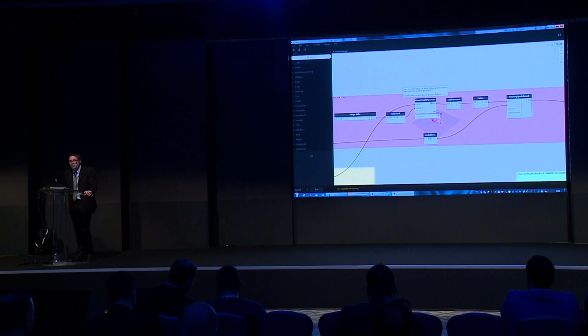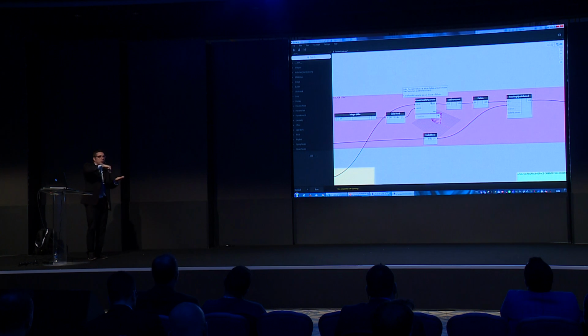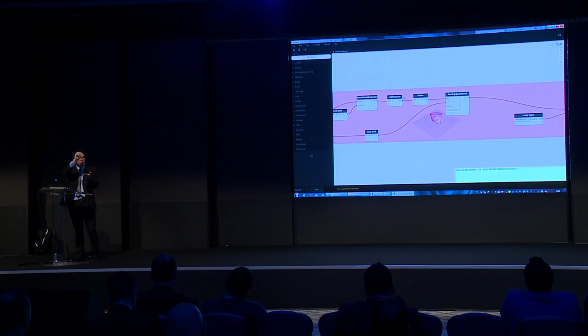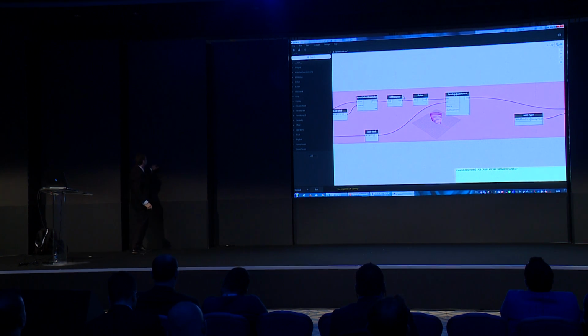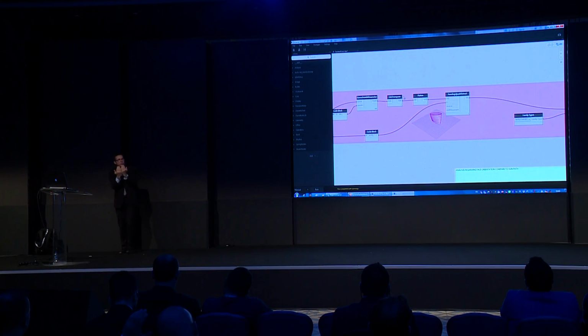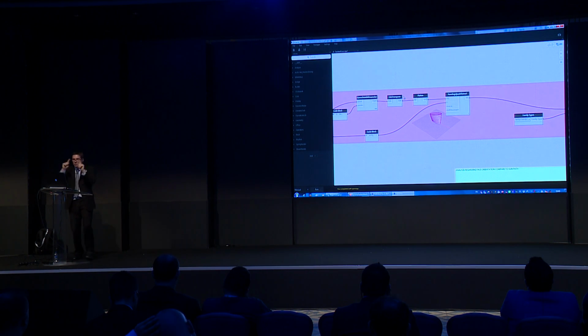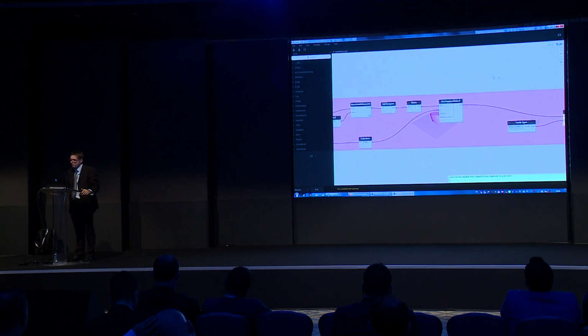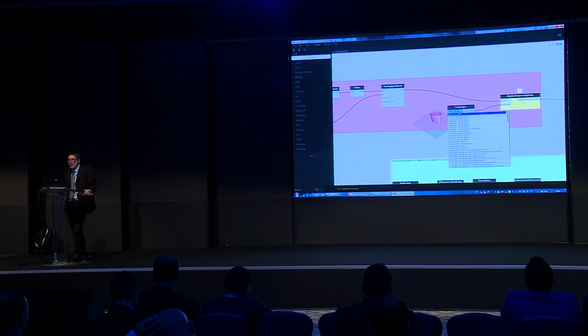And I create some points on each curve, okay? And I select all points and create a set of points with 1, 2, 3, 4. The next set of points is 1, 2, 3, 4, to have a right connection between all panels. And of course, after, I will tell the software to use the family 1.